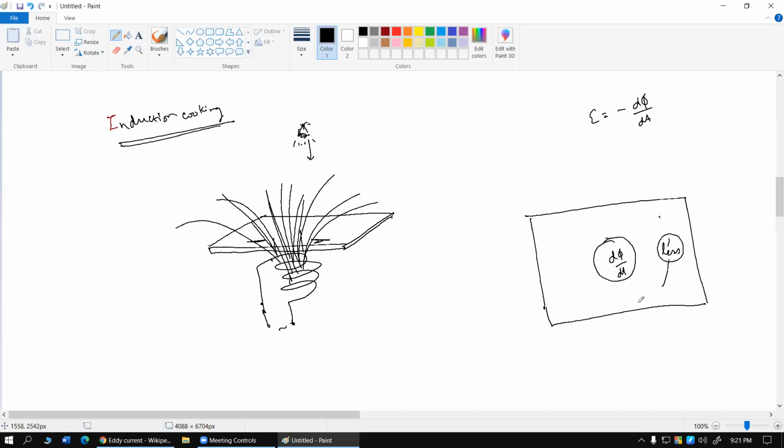So if I try to give you some numbers, for example, let's say as the cycle goes by for an AC supply, when the current increases from, let's say, 0 to maybe 10 ampere, let's say at the core, the phi, sorry, I wrote theta, the phi, let's say, increases from 0 to 100. Whereas on the outside region, so let's say this is del phi at the center, and this is del phi at the outside, let's say that changes from 0 to 20. So there is a difference of electromagnetic induction amount because of the concentration of the magnetic field lines.